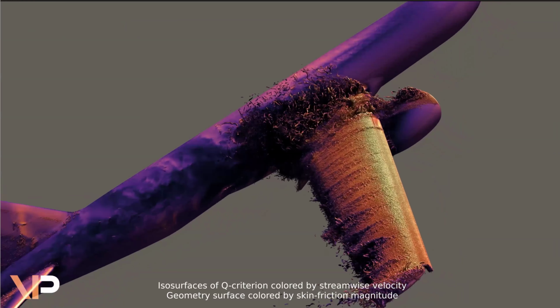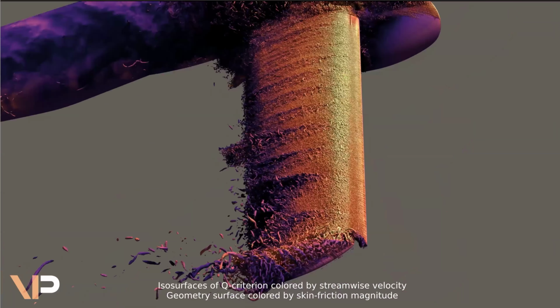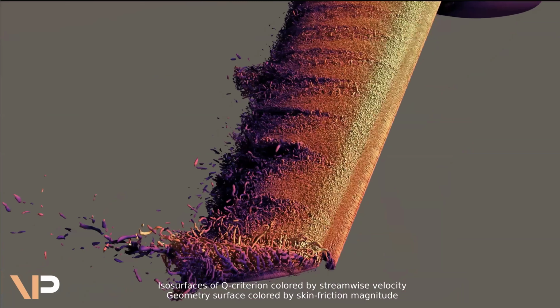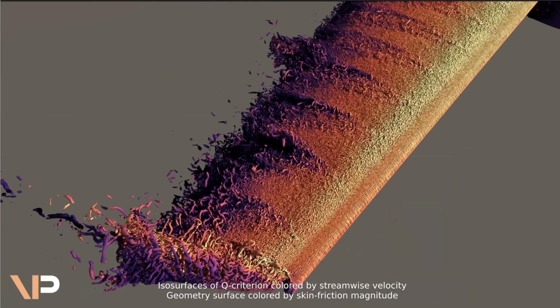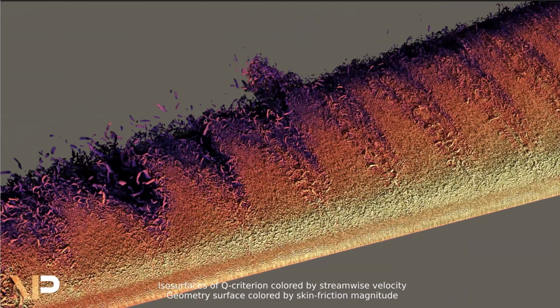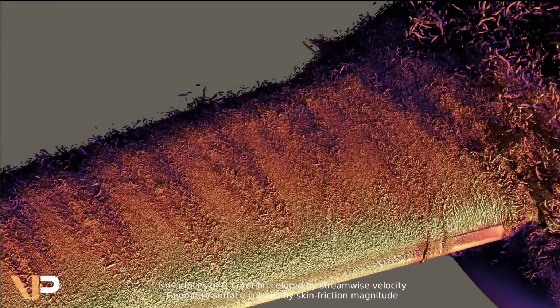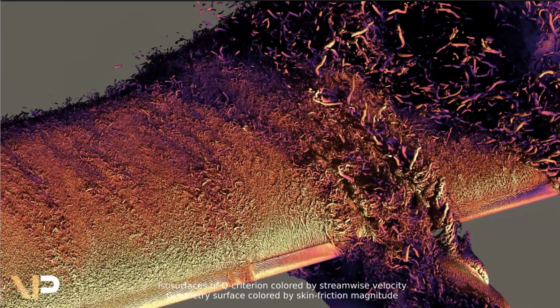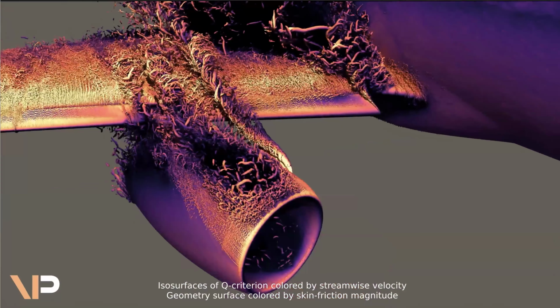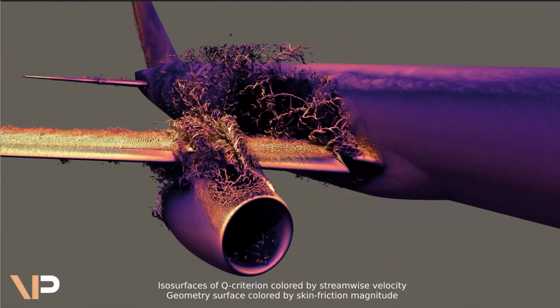Really, the thing to be taken from this is, if you do not resolve turbulent quantities, the inboard separation is being affected by the chine vortex, and the pizza shape separation is being affected by the slats, and transition is another thing. And even the flap separation plays an important role. Horseshoe vortex at this junction.